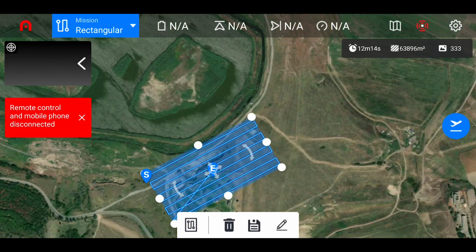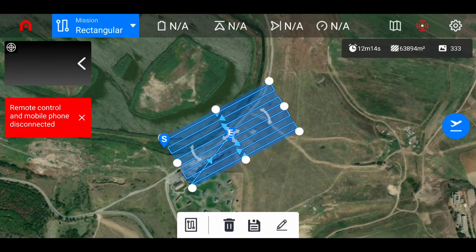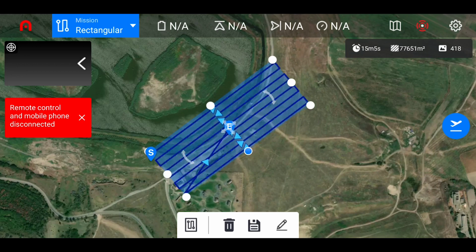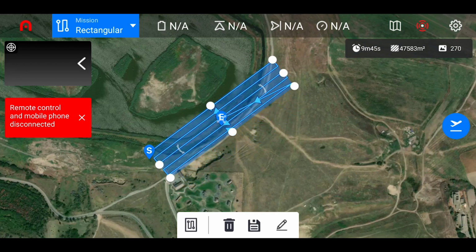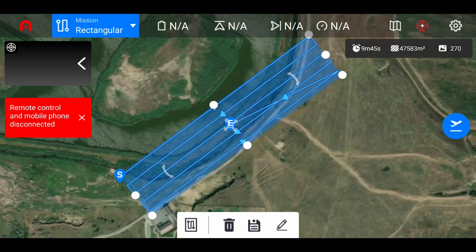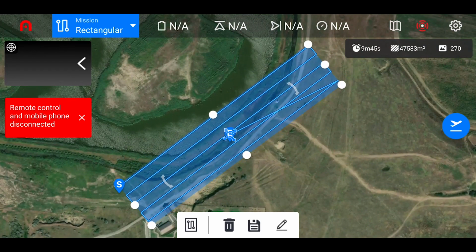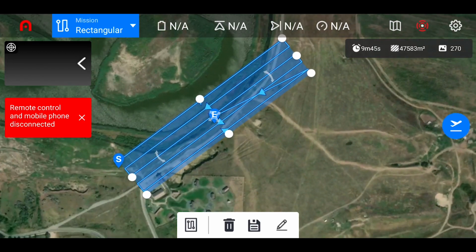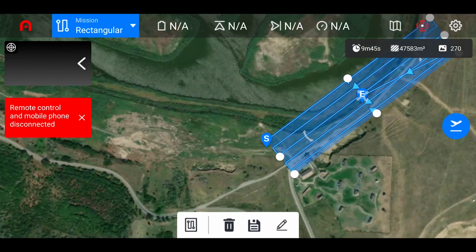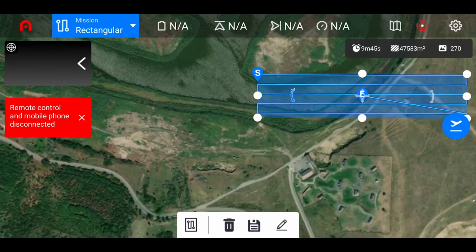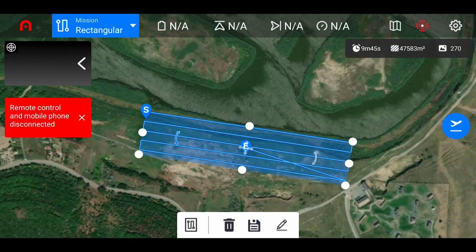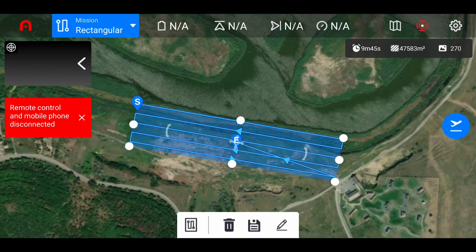At this stage, the user can still navigate the map and easily use the control points to rotate and pan the mission at his convenience. Also, he is presented with control points that can alter the flight plan on its length and width, thus increasing or decreasing the flight lines. The application automatically determines the time required to execute the flight, the area in square meters, and the number of photos with every modification to the flight plan.